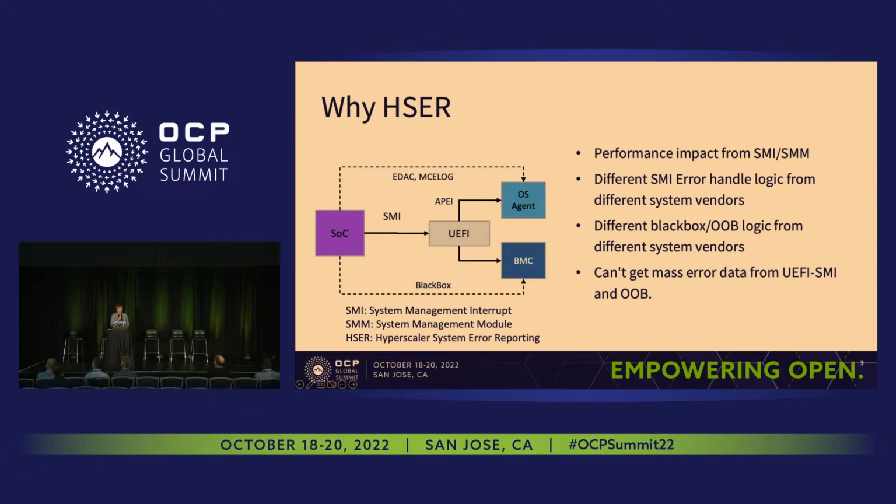Most companies right now are using BIOS or UEFI to pre-process the error domain so that the whole system error reporting can be handled within the hardware domain without involving the operating system or software. The problem with this mechanism is that system management mode, an interrupt mode, would affect system performance. The granularity of error is not small enough either. Meanwhile, once the error reporting fields require updating, a BIOS or UEFI upgrade is needed as well, which will affect system efficiency.